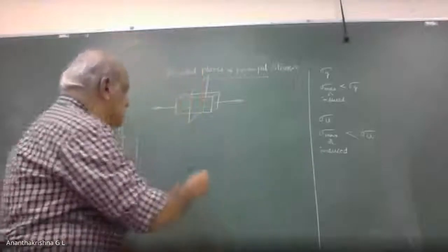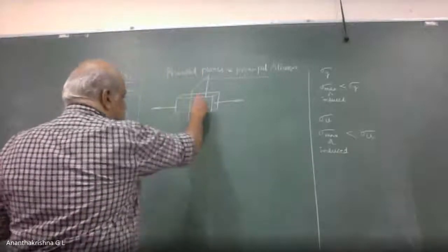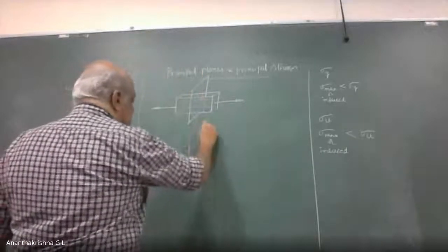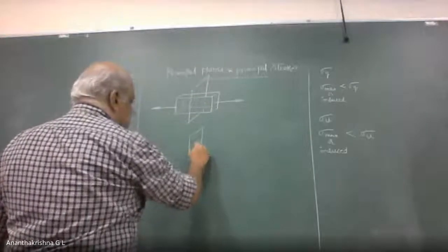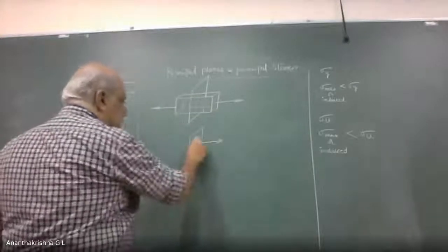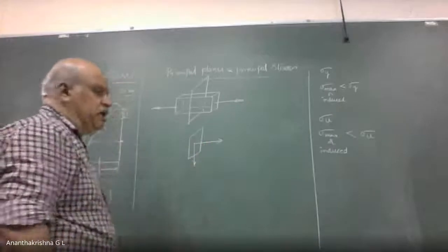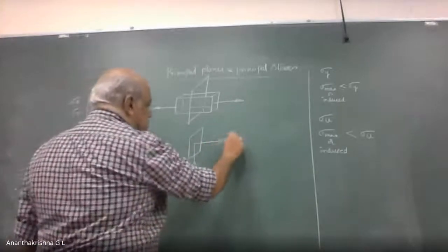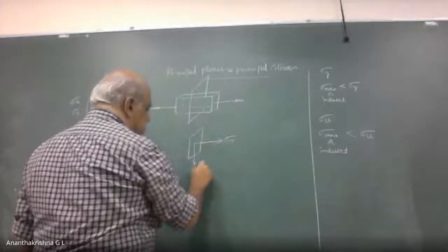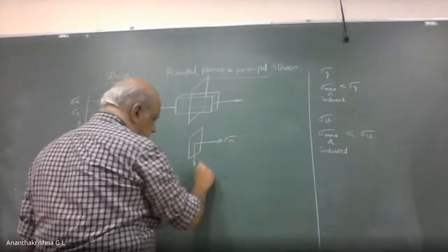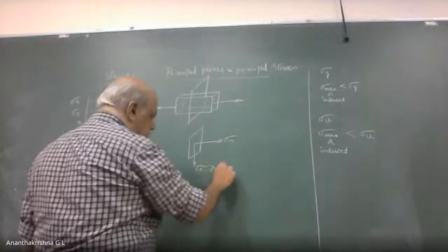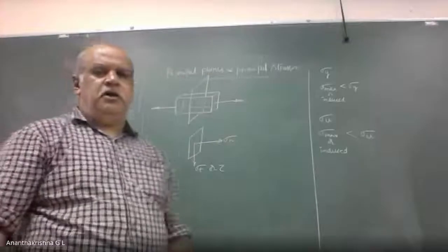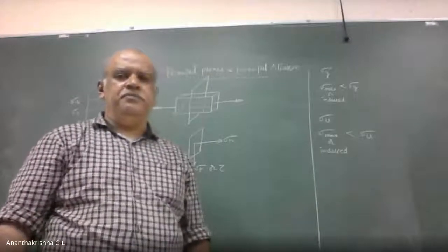When I take a section plane, two stresses are induced, one perpendicular and another parallel to the plane. Perpendicular to the section plane, we call it normal stress. Parallel to the section plane, we call it tangential stress or shear stress. Are you with me? Yes, sir.